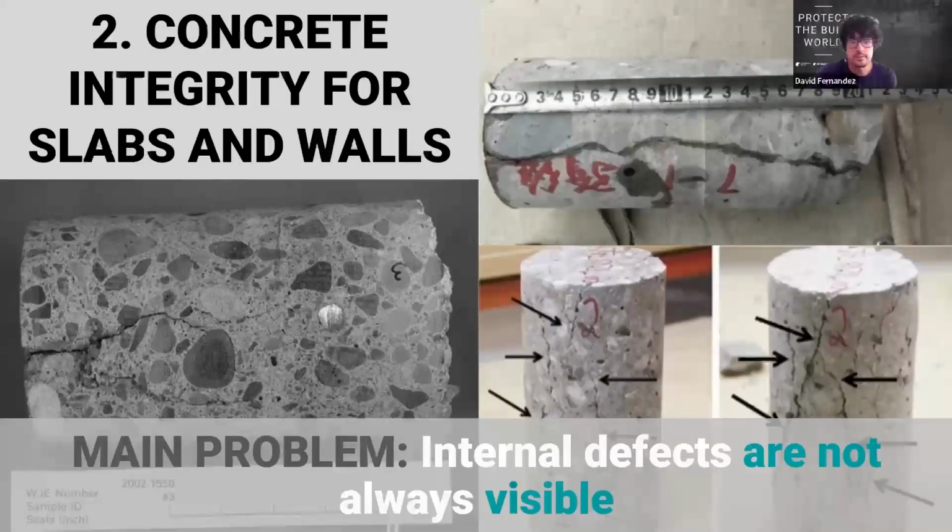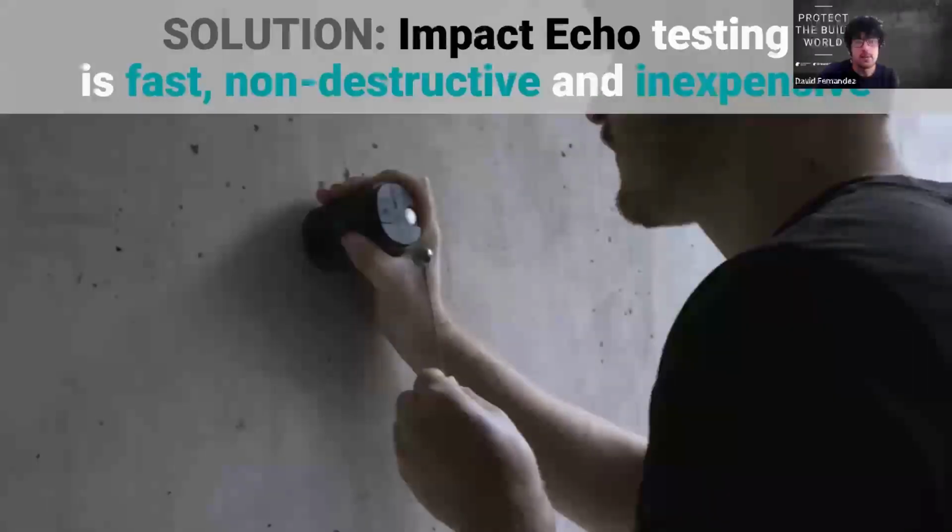It's really accurate because you can see the defects visually, but the problem is that we need to repair the concrete voids afterwards. So that's where Impact Echo testing is a really good alternative, because it's a non-destructive technique and it's also fast and inexpensive. So this is a very good technique if you want to avoid these destructive techniques that I was talking about before.